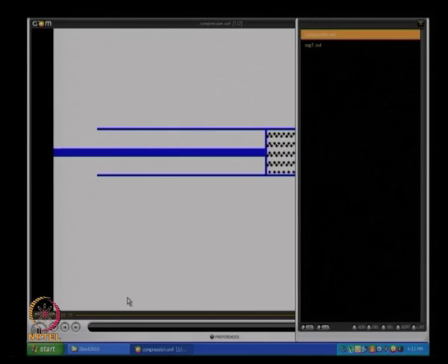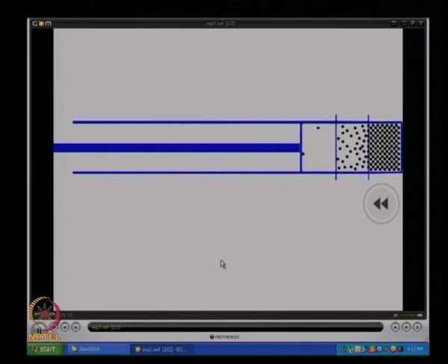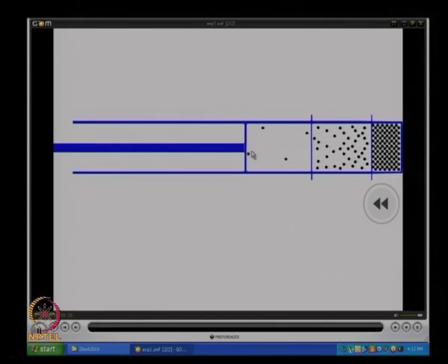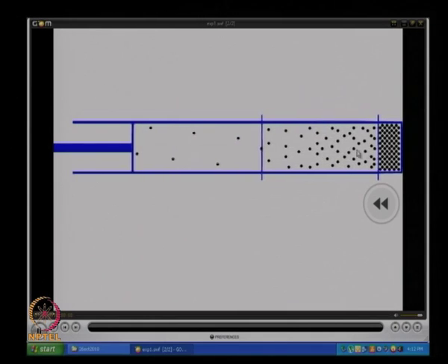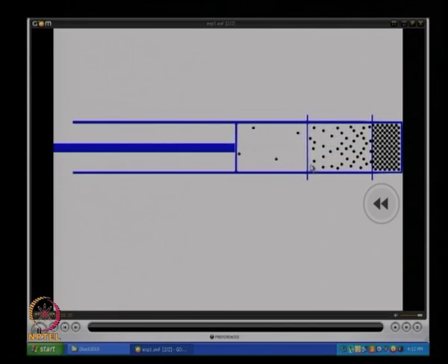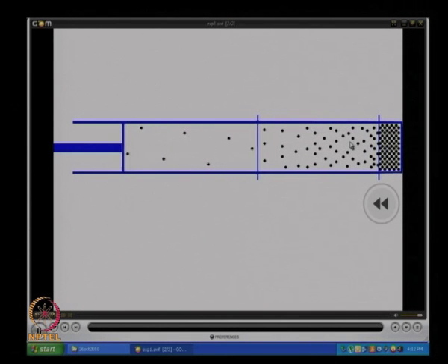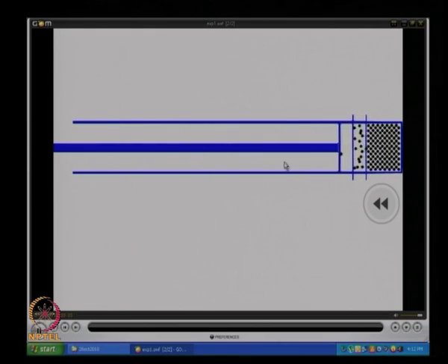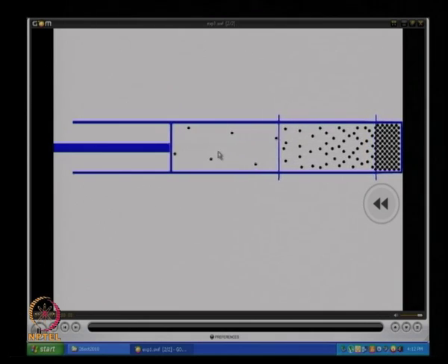Now we will look at another animation where this is the opposite. If the piston goes the other way, then the high pressure gas is now expanded to a low pressure gas, and it is expanded in a slow gradient, slowly. Okay. So there is a big set of expansion fans sitting in this whole region. There are so many expansion waves inside here. The density is slowly decreasing from here to here, and then after the last wave, the density remains constant. That happens in an expansion wave. Okay. These things we already knew.